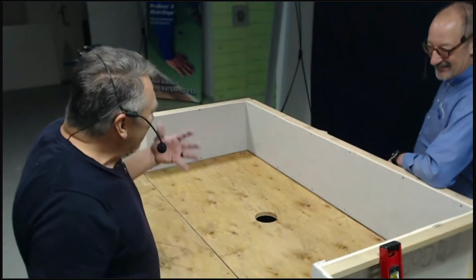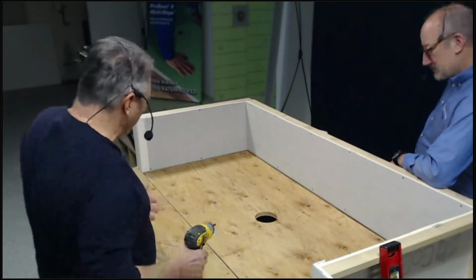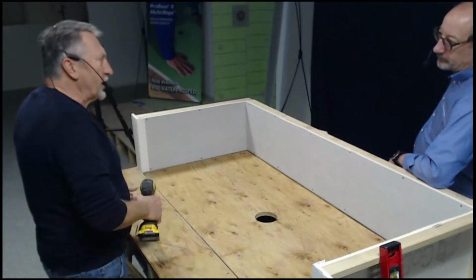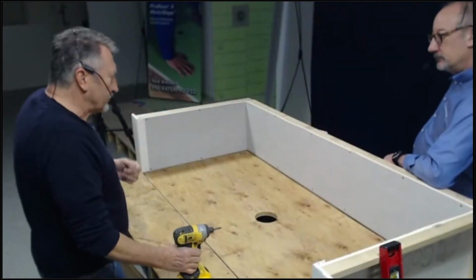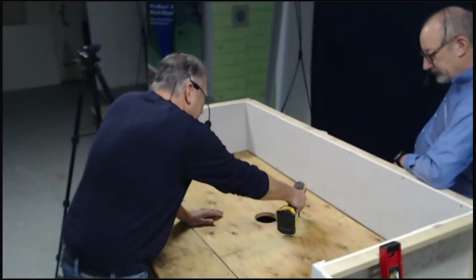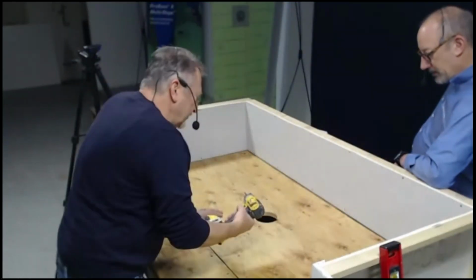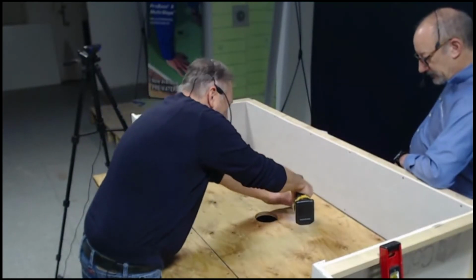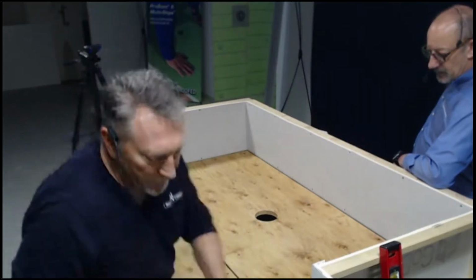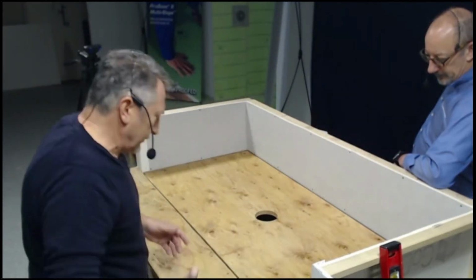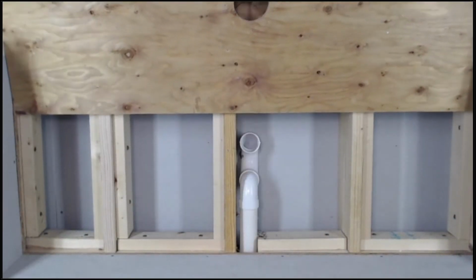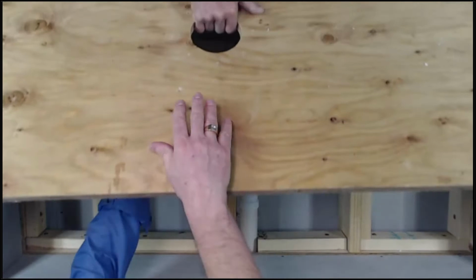Exactly. So then I'll go ahead and remove the substrate. I may want to cut it up in sections. Typically you're going to have ring shank nails. There's going to be subfloor adhesive in there, so you're going to have a little bit of a challenge maybe to get that out. So it's not going to be nearly as easy as what I've got here. Yeah, but for demonstration purposes, you've basically cut out the plywood. I've cut out, you're in here with a pry bar or whatever, popping this out of here. And I've cut my substrate out. You want me to take that from you, Dave? Yeah, take that out. Let me get that out of your way.